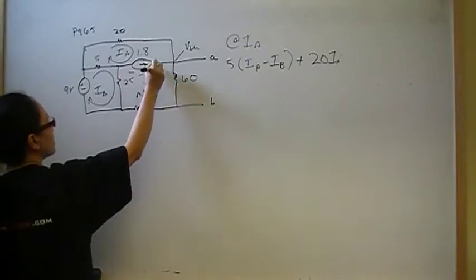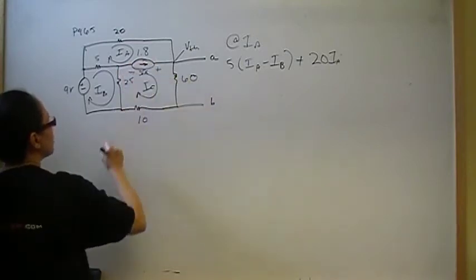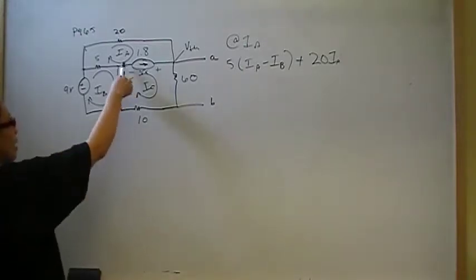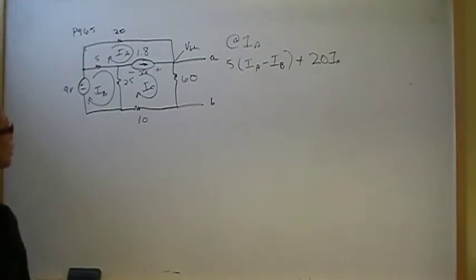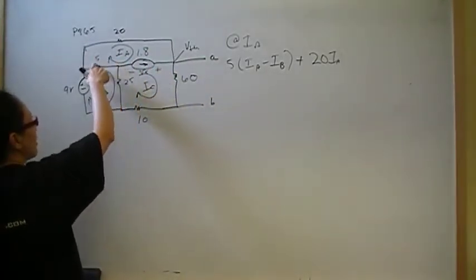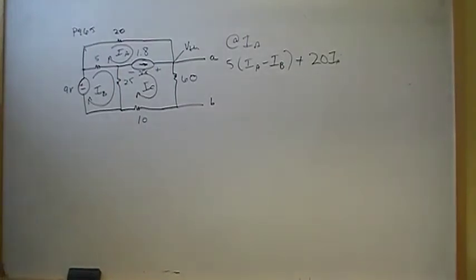So I'm going from minus to plus, and there's some Vx voltage drop there. Okay, now if you were super duper clever, you would say this border is a current, and since it's a current, I have a super mesh, and so I could just go around here like that and write my equation. But if you were in a rush and you didn't immediately see that, that's okay.